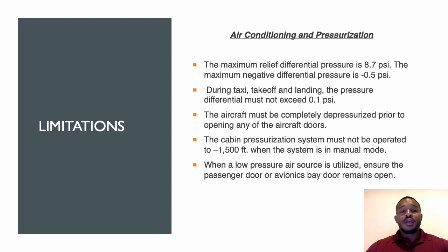So here are some of the limitations of the pressurization system in the CRJ. So the maximum relief differential is 8.7 psi with a maximum of negative 0.5 psi.